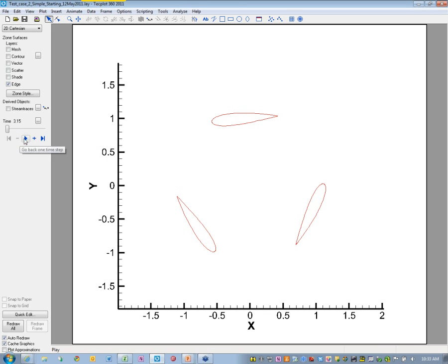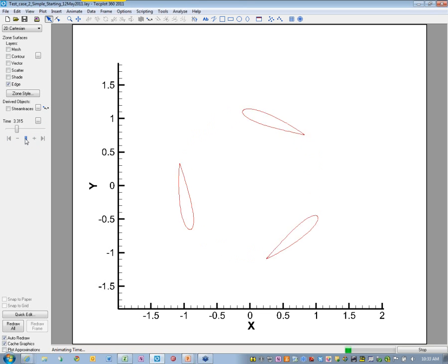Again, the one cool thing about the way that we handle data, the first time we load the data, we actually don't load it till it's needed. Now this is really important if you're looking at 1,000 time steps, which some of you are. If you have 1,000 time steps, and let's say that your average time step is on 10 million cells, which is probably not atypical, you're looking at not quite a terabyte, but probably 50 gigabytes of data, maybe more.